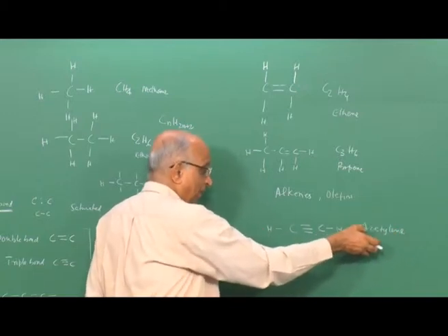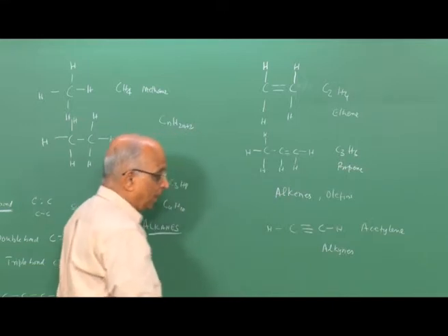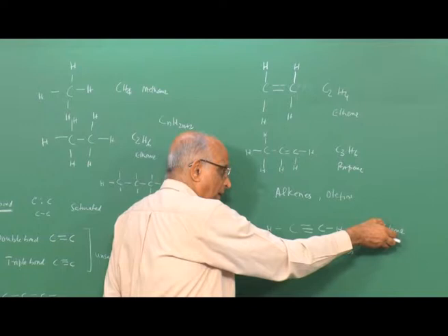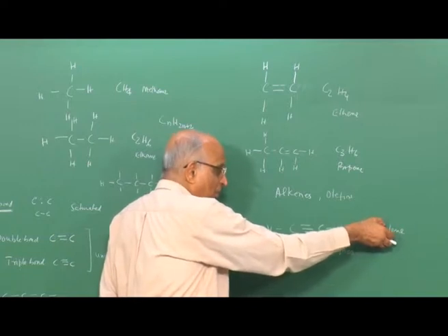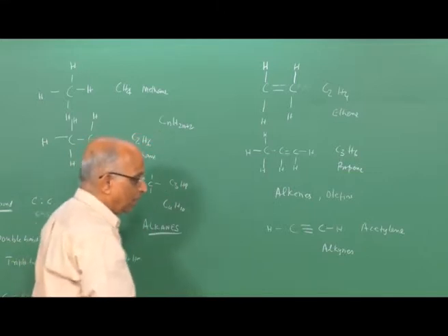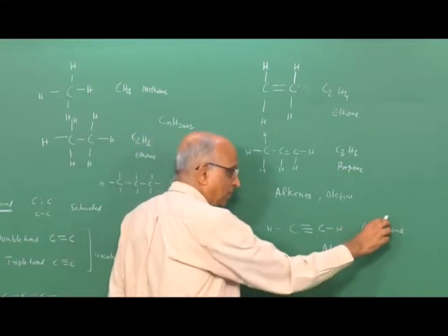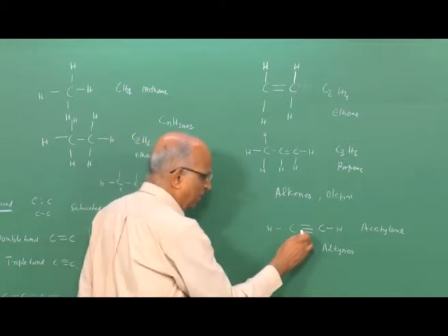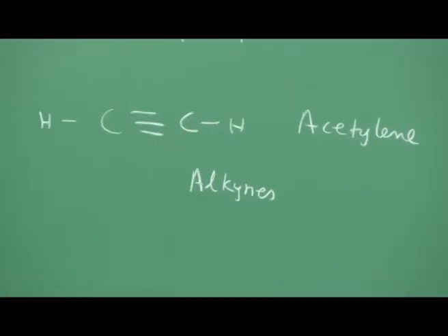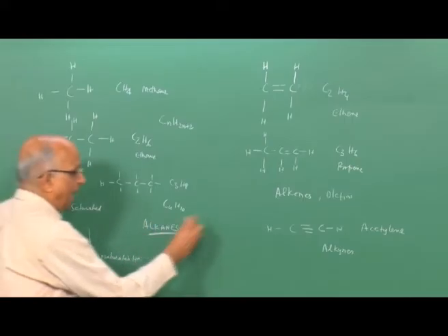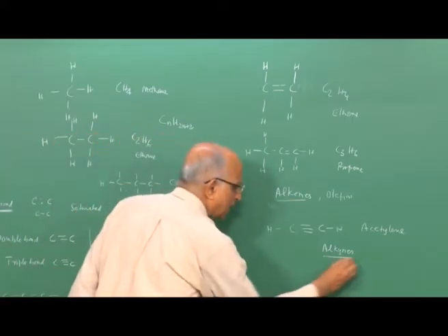We found its ignition energy is very low. It has a higher level of maximum overpressure in a constant volume explosion. We also saw that the dP by dt value, or the severity of the explosion, was higher, and this is acetylene, with the triple bond over here. Therefore, we generally classify hydrocarbons as either alkanes, alkenes, or alkynes.